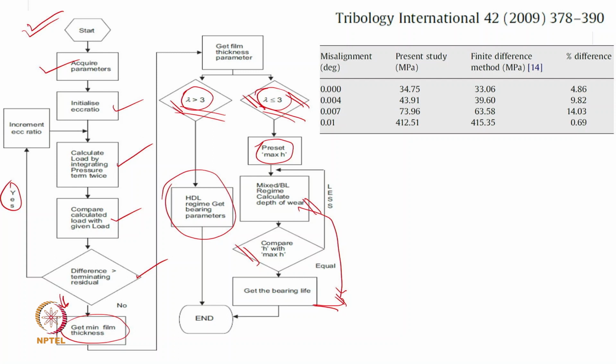Now we can estimate further what is the overall permissible limit. Now, what's the meaning of that? Initially I suppose the bearing wear is only 0.3 mm, and the permissible wear is 1 mm. So I know how much time it took for 0.3 mm, and using this kind of relation, when it will be equal to 1, using a theoretical calculation or simulation, I can find out what will be the bearing life. Now when we are introducing the misalignment, the major issue comes.